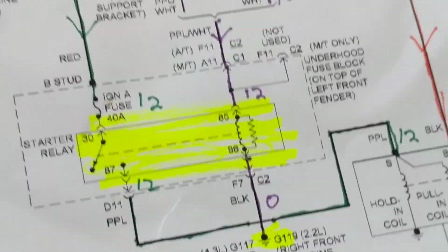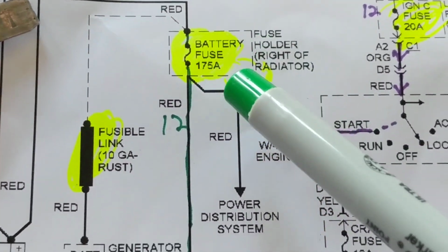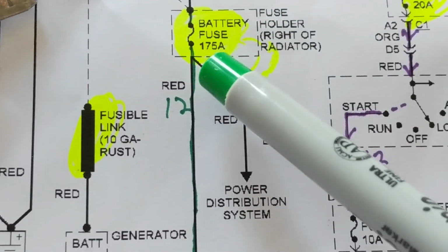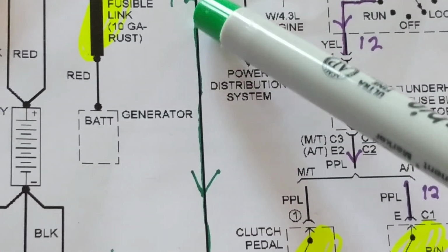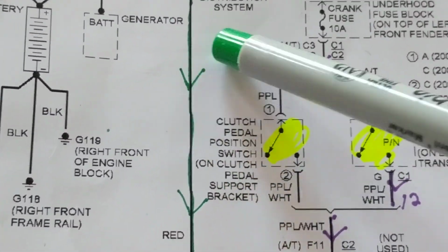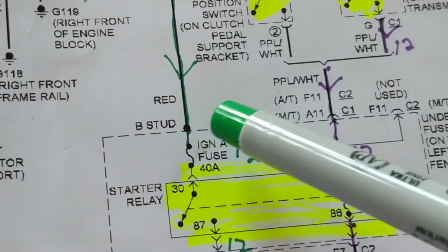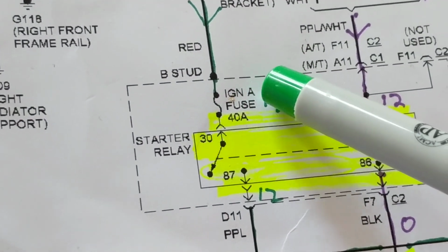So therefore, I give you the voltages. Red wire coming in, current flowing, coming into this fuse, coming out of the fuse, red wire at 12 volts. Schematics don't have that. I show you the current flow. Schematics will not show you that. Still continuing to a red wire, going into this fuse. What's the fuse?